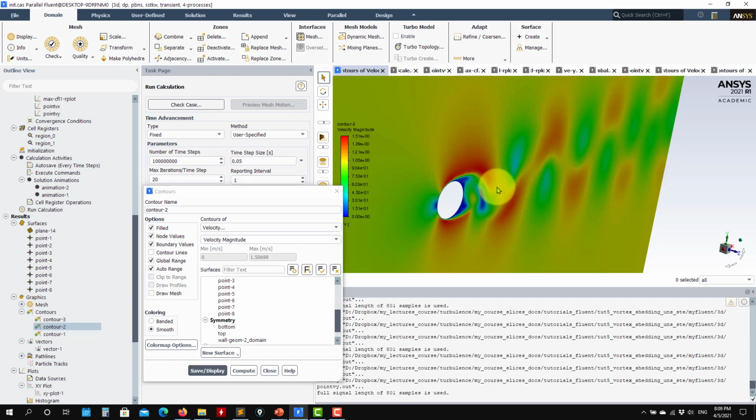And remember that that is very important. We have to talk about that. So when you go to 3D, you will see that usually all this energy is lower. This doesn't mean that it's wrong, but it is the right behavior because it's less energetic. You have the actual physics, you have the vortex stretching, how the vortices dissipate, the separation, how all this is scaled. Instead here, you don't see that vortex stretching.